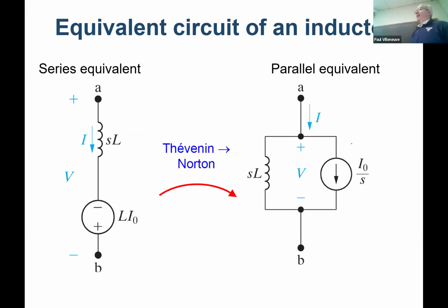So in the Laplace domain, we have this circuit. All right. Questions on that? Because these two are very important, because this is what your circuit model is going to look like. Instead of an RLC, you're going to have an R and an L with potentially a power supply and the s multiply there. And the capacitor one, we're going to see in a second. Questions on that? Feel okay so far?